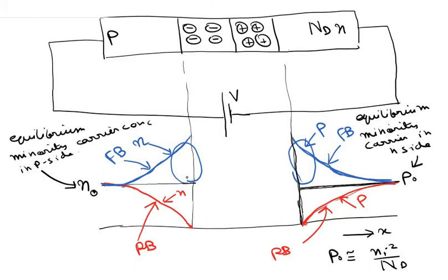Okay, so I repeat again that during forward bias, this excess minority carrier concentration has built up just outside the depletion region. Now as the diode goes from forward bias to zero bias condition, the total excess minority carrier concentration, which is basically proportional to the area under this curve, must be removed before the diode can actually go to zero bias condition.